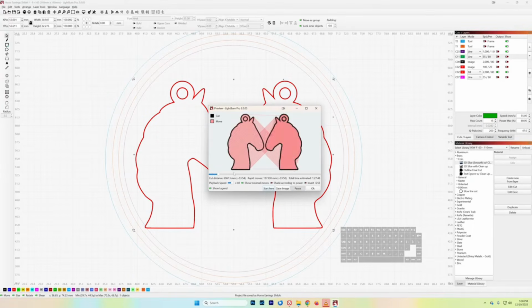And the reason that we make that little, thin width is because if you just use the width of the laser beam, especially with brass, it heats up very quickly and then it cools very quickly, and it may not ablate. And so you're just basically melting it, and then it solidifies back in place. And so having that small area there sometimes helps cut it out.